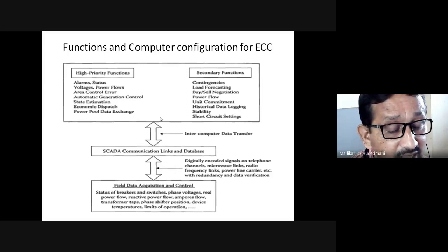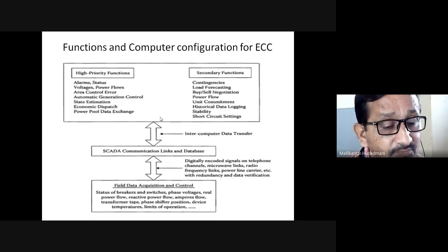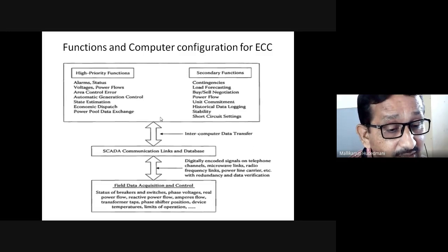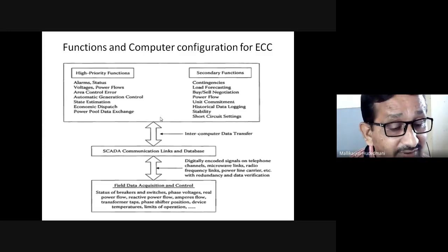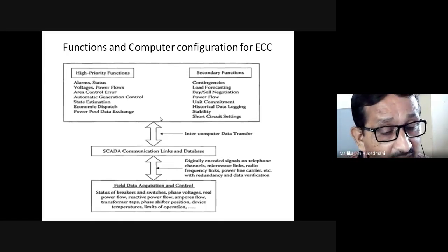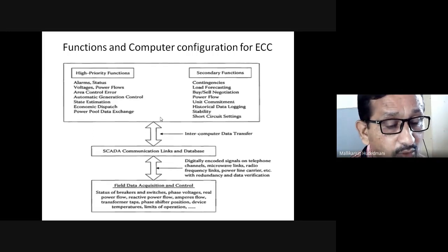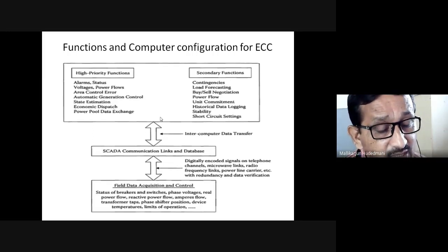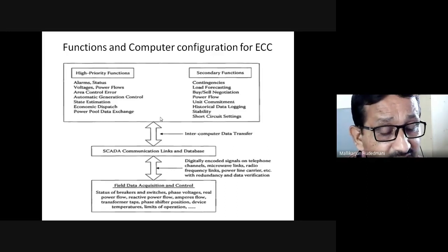the area control error. If the area control error of a locality is zero, there is no further change in the command. The command that was simulated should continue. If demand is increasing and error is increasing, then the error has to be nullified. To nullify that, generation has to increase accordingly. In that way, an automatic closed loop is simulated for this automatic generation control. That is a priority aspect because the power system has to address P balance and Q balance at every moment of its